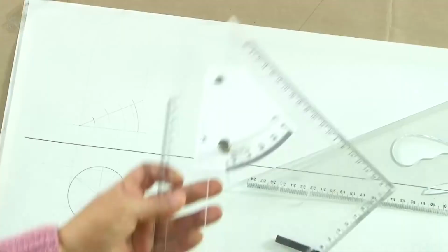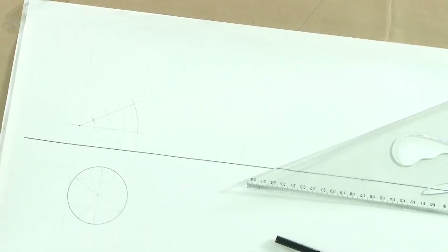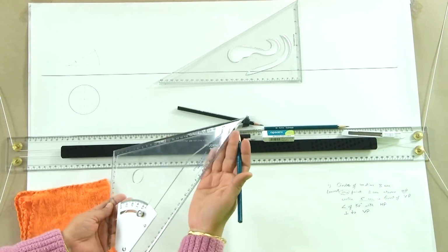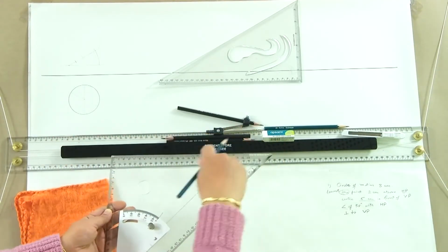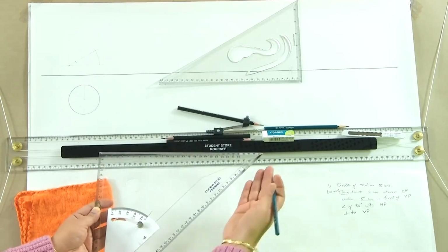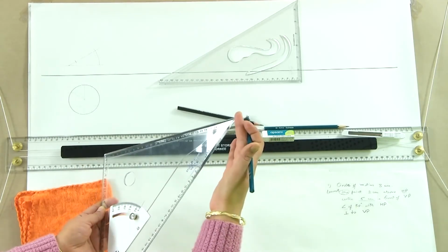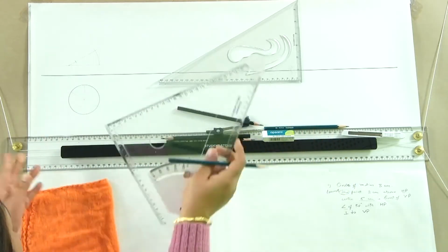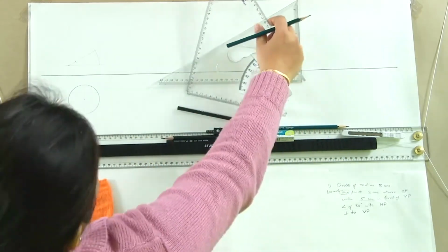When we incline this plane, which was parallel to HP, the points move, but their horizontal projections remain the same. So, their vertical projections change. A point which was here has gone up there, but horizontally it still is falling in the same line, which is the principle which we have employed here.